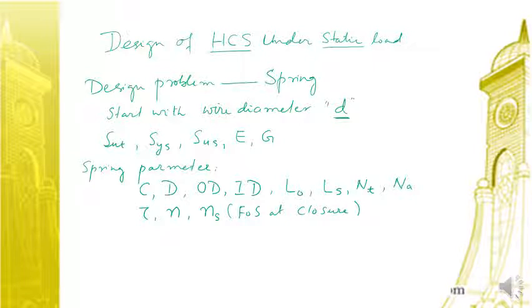We need additionally to determine the critical length of the spring, and we need to compare this with L0, the free length of the spring, so that we can determine about buckling.